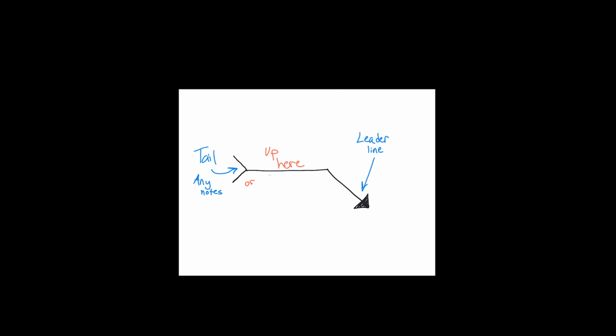And before moving on, we need to address that the bottom side of the reference line is what we call the arrow side. The top side is what we call the other side. And this is going to be crucial to remember, so that way, wherever the reference line happens to be pointing to, you're going to know what welding information pertains to exactly where the line is pointing to.